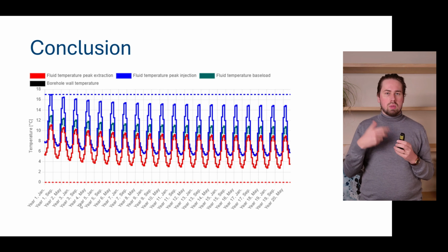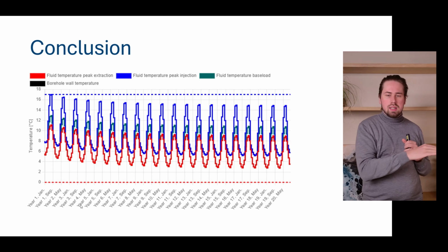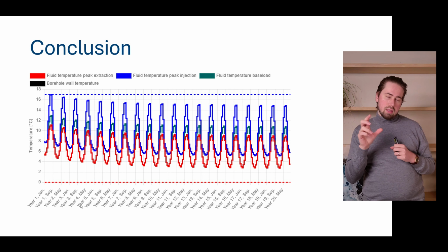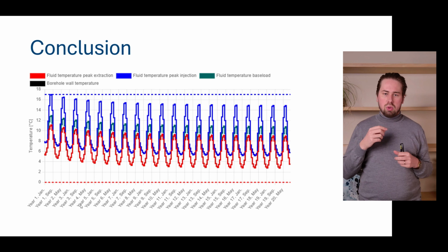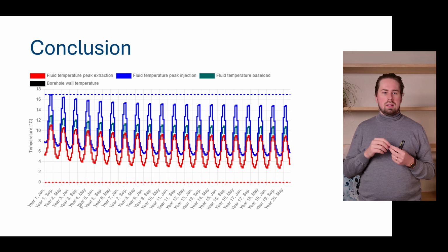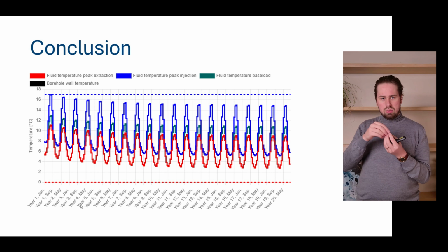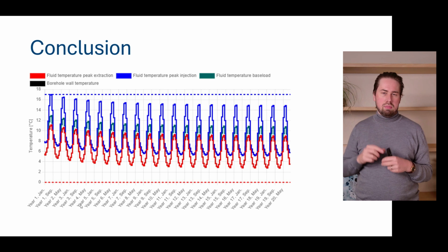You see here what we discussed today, this downward going trend. You clearly see here the G-function because it goes down steeper in the beginning and over the years it flattens out. And you also see the effective borehole thermal resistance as being the important factor when it comes down to calculating the difference between the borehole wall temperature and fluid temperature.